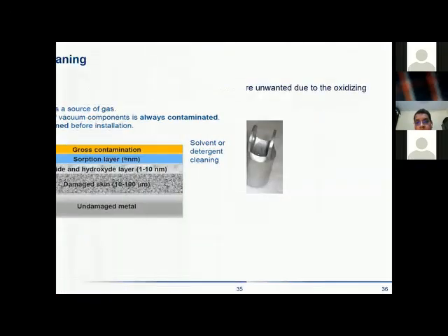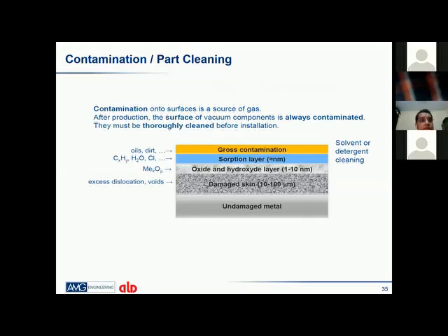So most of the times we see the furnace has been properly maintained, the vacuum level is completely maintained, and we are getting a very good leak rate. But whenever the parts come inside, the parts are not getting bright, and the vacuum level is sometimes not reaching the expected level. That can be because of part contamination. This slide is showing that part contamination and part cleanliness are equally important if we are looking for a healthy life of the vacuum furnace.